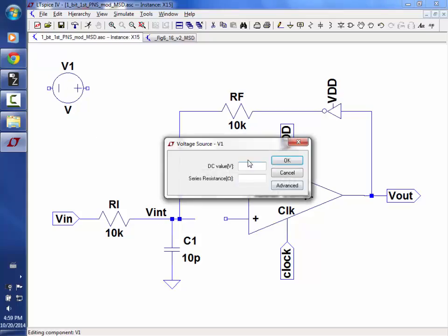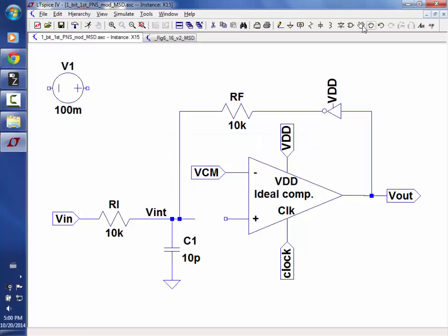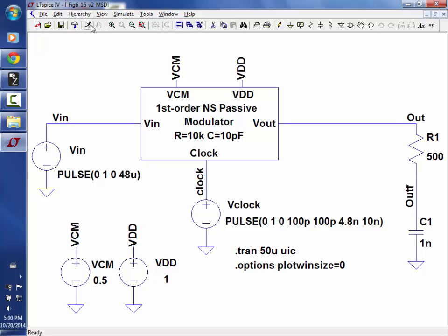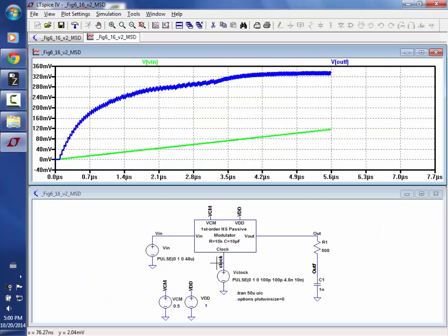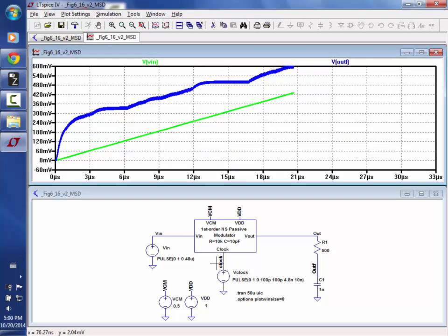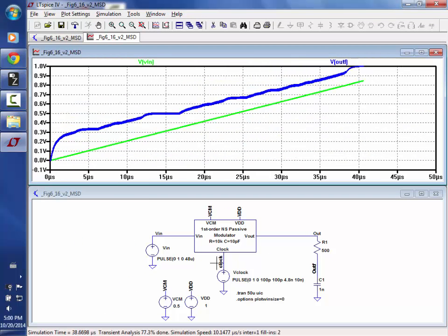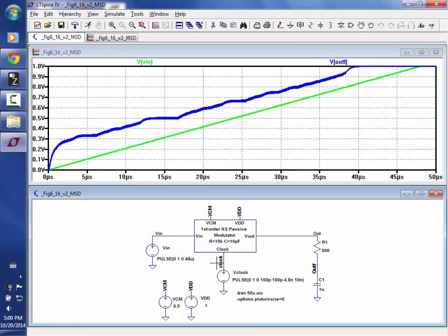Right click there. I'm going to put 100 millivolt offset, and I claim it's going to shift the curve. And hit run. Whoops. Save. Save. Close. Run. Does everybody see the blue went up by, on average, 100 millivolts or so? It's non-linear, but you have that issue here.